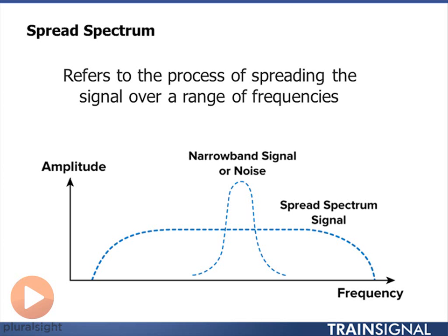But remember that 802.11 wireless LANs were defined to operate in a noisy, interfering kind of environment. So if I spread my signal across a wider band and there's some interference in that band, then the probability of me being able to recover that signal is much higher. And so spread spectrum is a technique that was defined in the early part of 802.11 because they knew that this was a shared spectrum. And it is exactly what is suggested in this graph, a way of spreading your signal over a much wider band when it's transmitting.